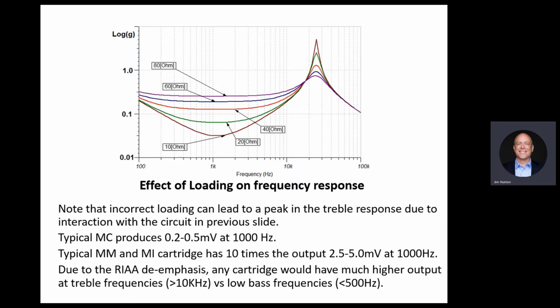Okay, line level 0.3 volts nominal. Peak, not peak to peak, 1 volt peak to peak. So if we are dealing with 0.2 millivolt to get all the way up to 300 millivolt, that's 6,000, a gain of 6,000. Okay, voltage gain. The 2.5 to 5 millivolt, a little less, by a factor of 10. So it'll be still a gain of 600 to 1,000.